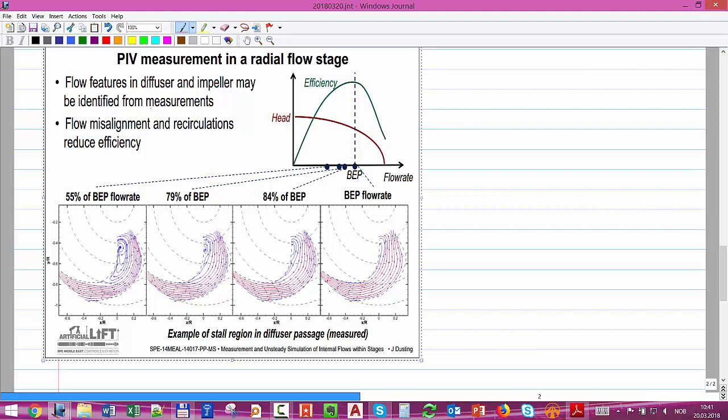That's how I design. But if the flow starts to be less, then the angle or the velocity with which I'm entering that passage is not anymore here, but it will be like that because you have a lower velocity. So it doesn't follow perfectly the passage that you have, but you will have some detachment of flow and some formation of eddies.